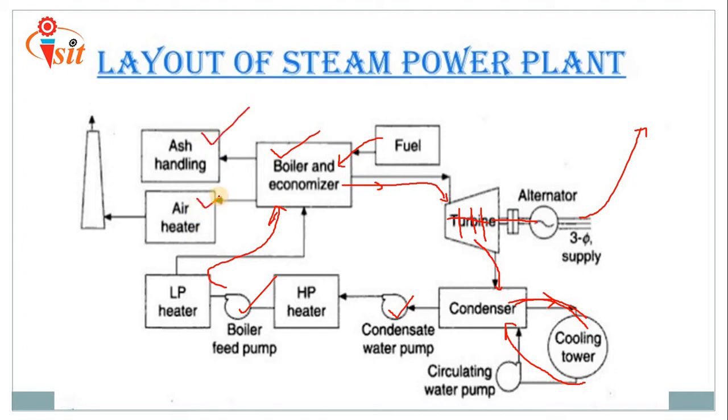So why is the air heater necessary? The air heater is necessary in order to avoid moisture in the ash. When the coal is in pulverized form, we must control its moisture content. That's why heated air is necessary. And once combustion is over, a tremendous amount of gases is produced. Ash is also produced, and that ash is responsible for pollution, and it is continuously moving through the draught.